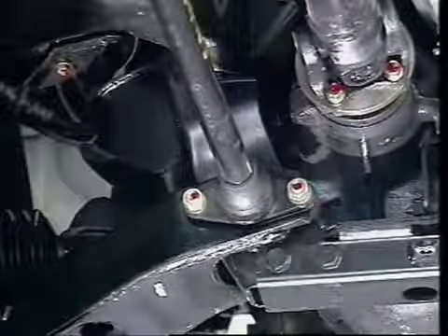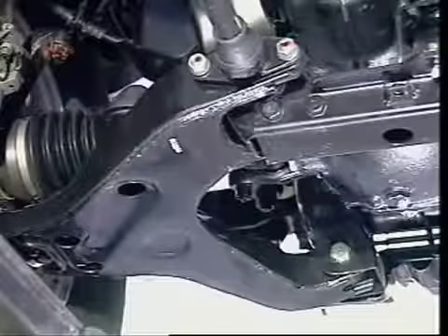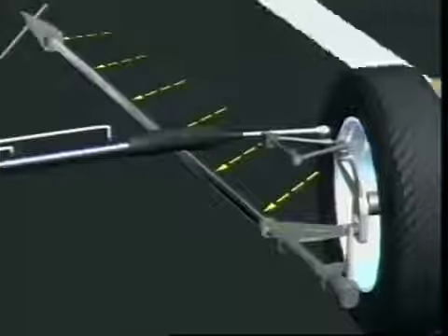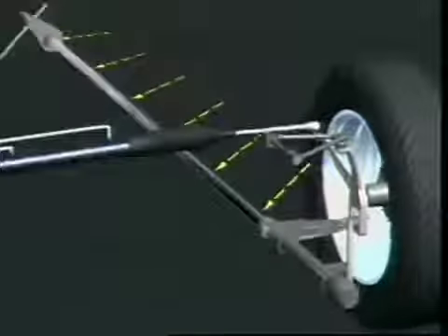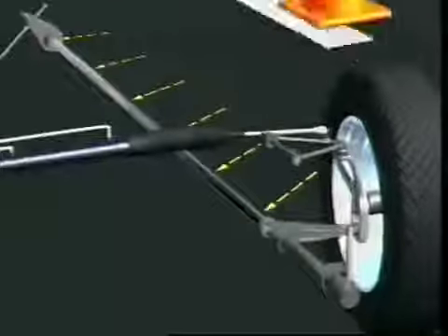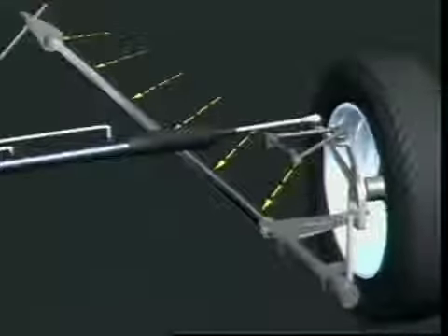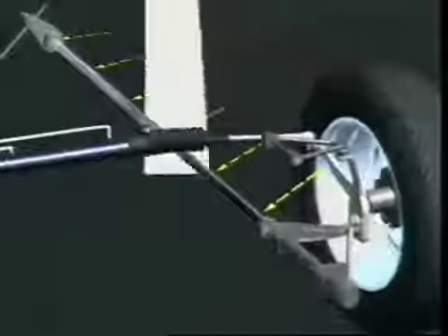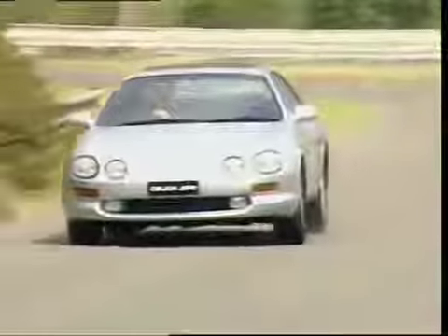The torsion bar is attached at the inner fulcrum point of the wishbone, or control arm. As the suspension is deflected, it twists around its center. It can be fitted to the upper or the lower link, depending on the type of vehicle. The upper link is shorter than the lower one, irrespective of the springing method used. When the suspension is deflected, the unequal lengths allow the track of the vehicle to be maintained near constant, but with some changes to camber angle. Generally, when the car leans during cornering, the inner wheel leans outwards at the top, and the outer wheel leans inwards. This helps to maintain maximum tire contact with the road surface.